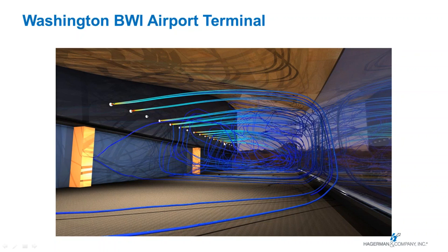And what the designers were trying to do was make sure that the air streams came in and washed over the glass, such that the solar loading on that glass wasn't going to create hot spots and, during cold weather or inclement weather, get condensation. So it's important that it would wash away. We also got this thermal barrier up here, so we don't want to disturb that thermal barrier, and that creates a nice insulating layer. There's no way you could have envisaged the performance of this system without doing CFD.